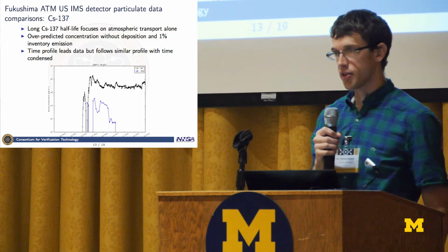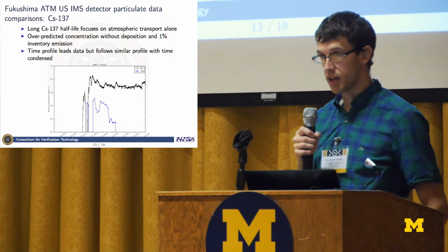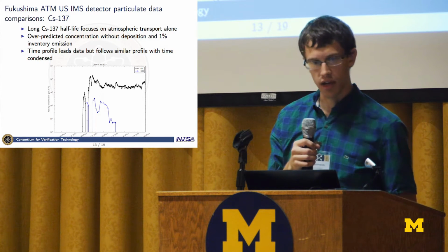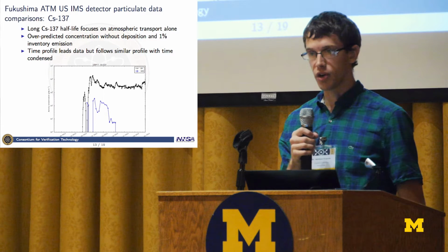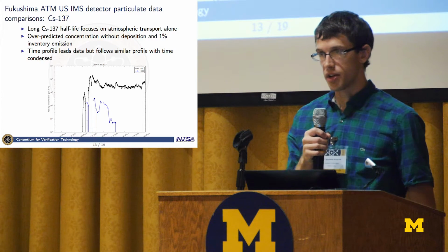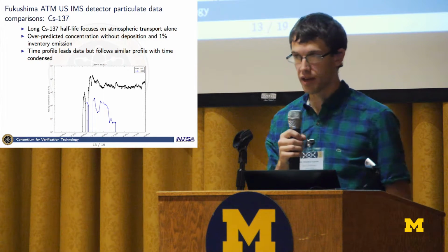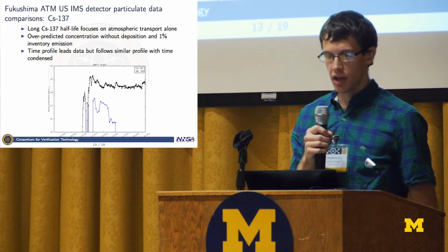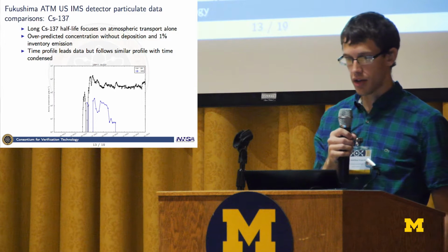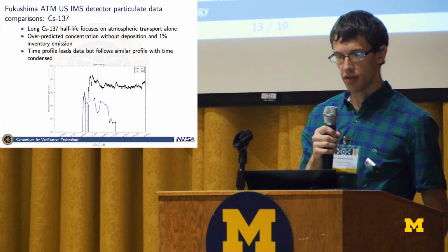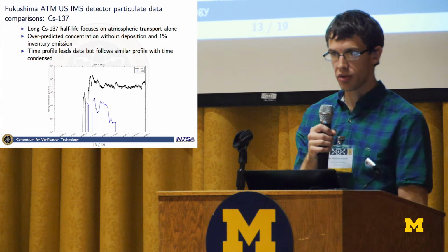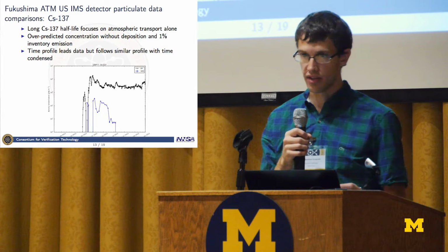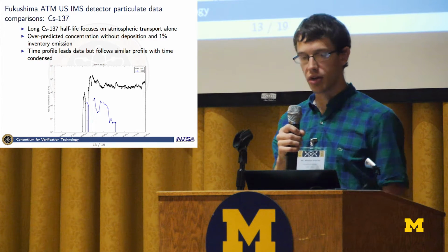So to me, this is indicating that our atmospheric model is not accounting for the deposition correctly. Indeed, it is actually turned off in this simulation, and the reason being because if we turn it on, we see no data. And this is at a station in Wake Island, actually, as well. So this indicates to me that our FLEXPART simulation has some real problems with the deposition model and definitely needs some improvement. But you can see that temporally we're getting kind of the rough temporal behavior. We have a lead on the first peak there, and then the next two biggest peaks, you can kind of see that those are in the data as well, but they're sort of stretched out. So to me, this indicates that we're not getting the atmospheric transport or maybe the release time dependence correct exactly. So if we spread out the release a little bit more in time, it'll probably look a little bit better.